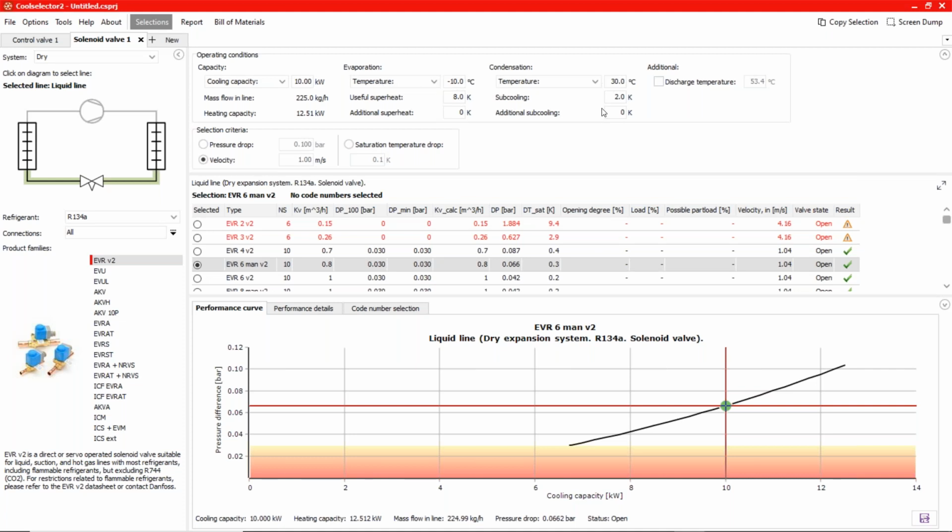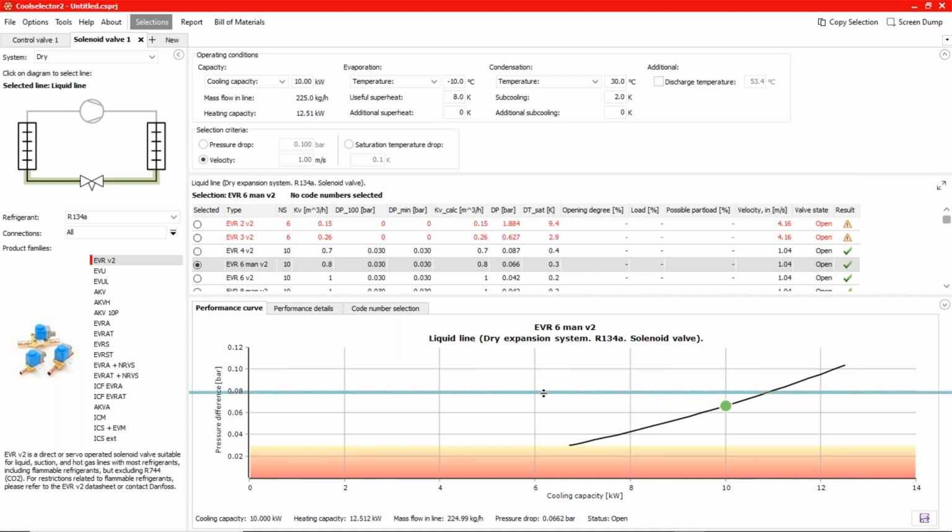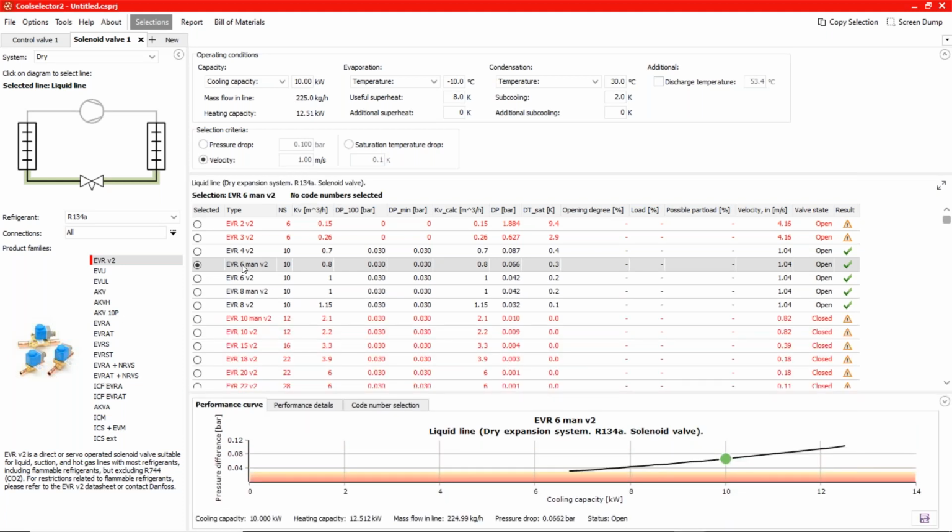And here I think there are some important things to remember, not only the condensation when you select this line component, but also the subcooling value, if you really intend to go further with the selection of the components. So let's keep this at 10 kilowatt, which is the real capacity of the system. There you go. It's marked, going for the ABR6.